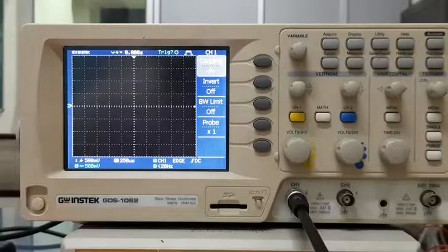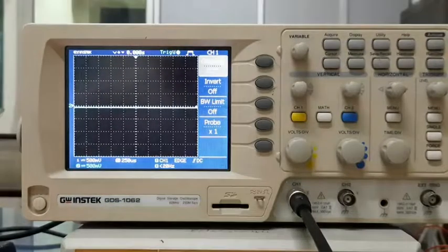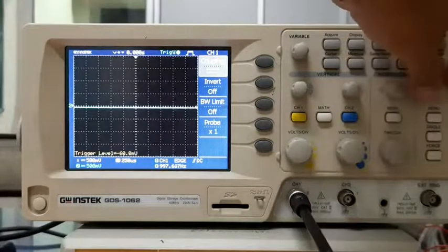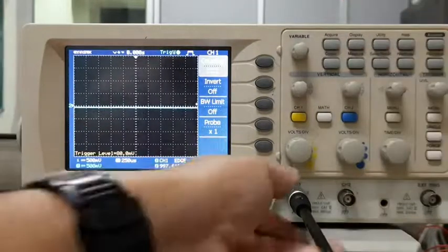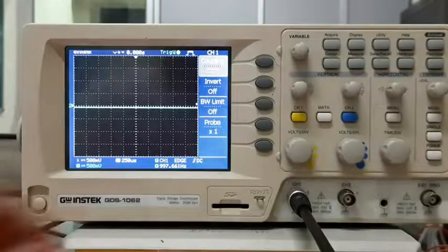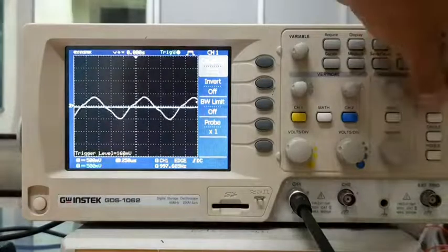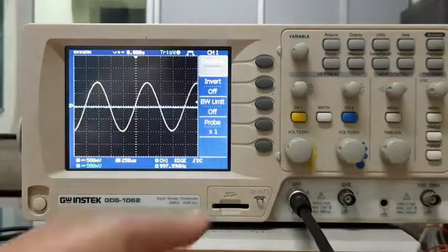The channel 1 is basically grounded, so no input is going inside. And then I can again select this as a normal AC coupling, right? And I should be able to get the signal. Okay, so channel 2 was off, so I'll just switch on the channel 2, and then you see the channel coupling. I think there is some, okay.